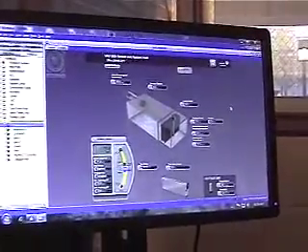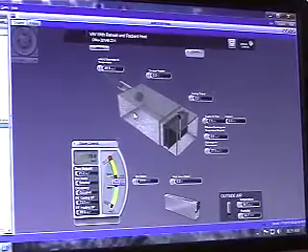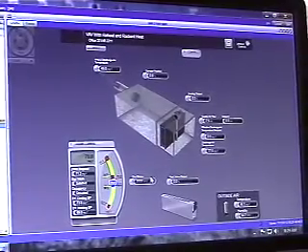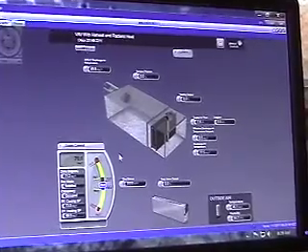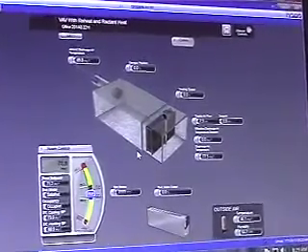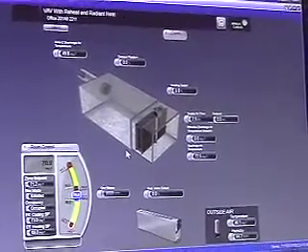So I guess real quickly, why we're here, this might be a good point to talk about some of the sequencing with these VAVs. We mentioned it before when we were walking through. Cooling is pretty standard. You're trying to maintain the temperature. The further away you get from your temperature, the warmer it gets, and the VAV damper is going to open up more and more, up to the maximum cooling set point, to provide that cool 55, 50 degree air into the space.